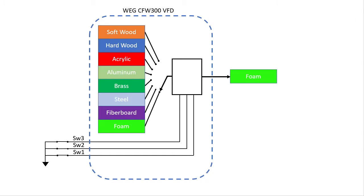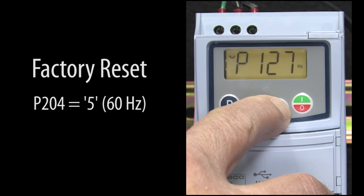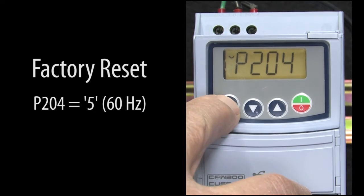Given 1 to 3 digital inputs, you can select up to 8 possible predetermined frequencies. And it's easy to do. But there are a couple things you need to be aware of when implementing multi-speed, so let's do a couple quick examples so you can see what to look out for. Before we get started though, let's reset the drive to factory default so we're all starting in the same place.